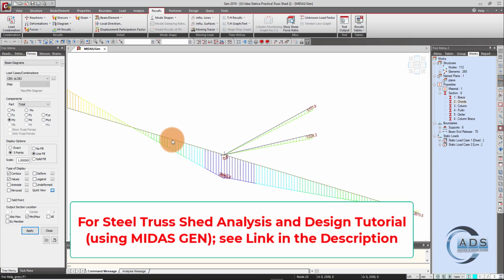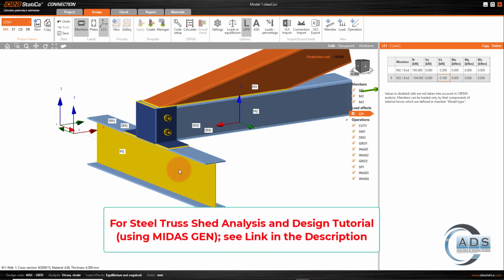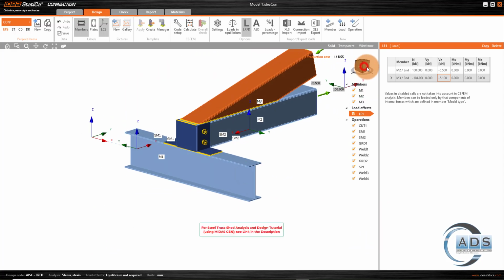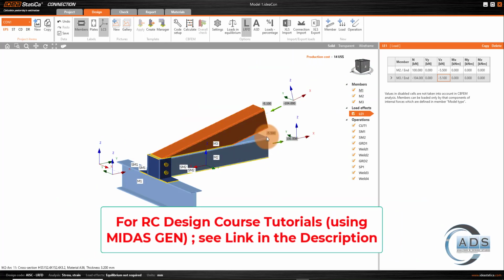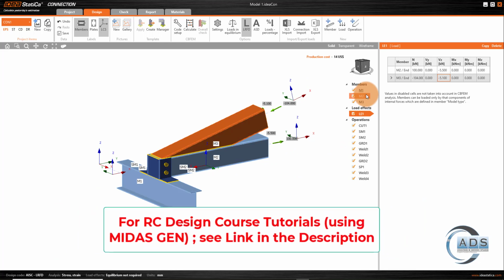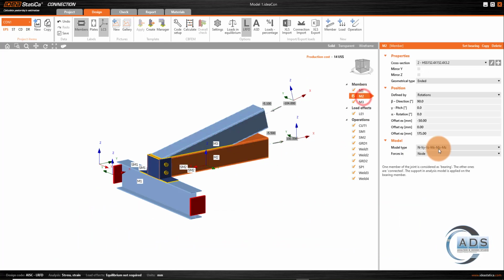There is only a bending moment at the beam, but since this girder, this beam, is acting as a bearing member here, we will not apply loadings of these two members, since these two members do not carry any bending moment at the joint. So let's change its model type to N, Vy, Vz.